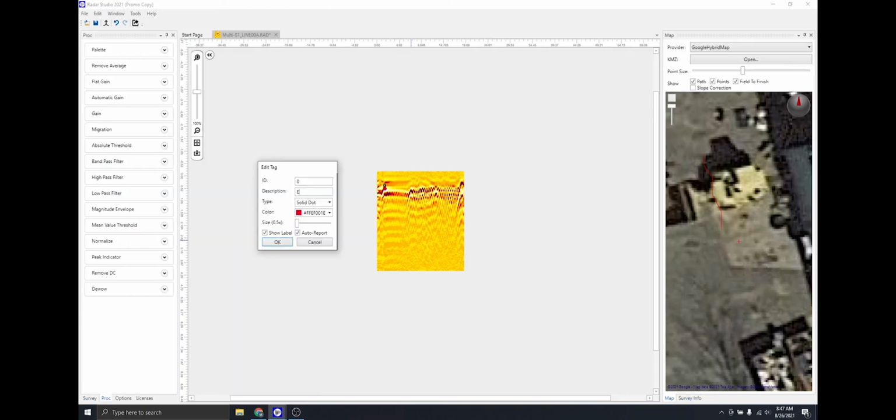Make sure that you have unique point names for each unique feature, or features that should not be connected to each other will be when you generate line work.